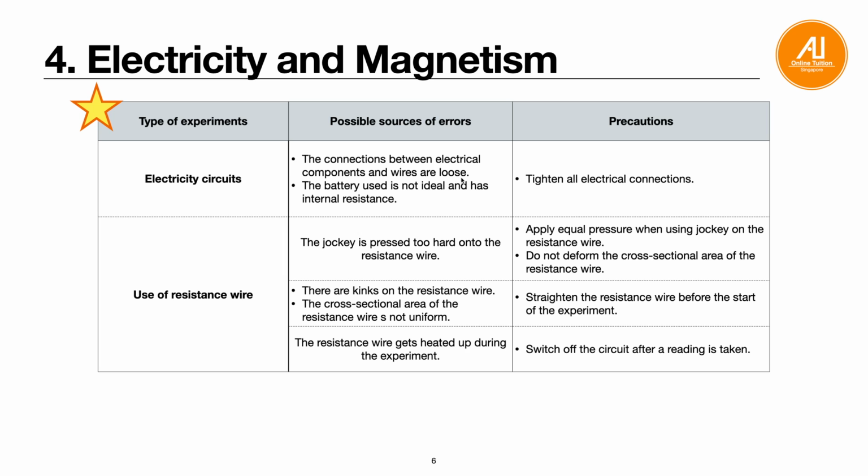Make sure the connection is all tight, from the wire to the resistor, or from the wire to your voltmeter or ammeter, or even to the battery. Make sure there's a physical metal to metal connection, not just loosely connected.